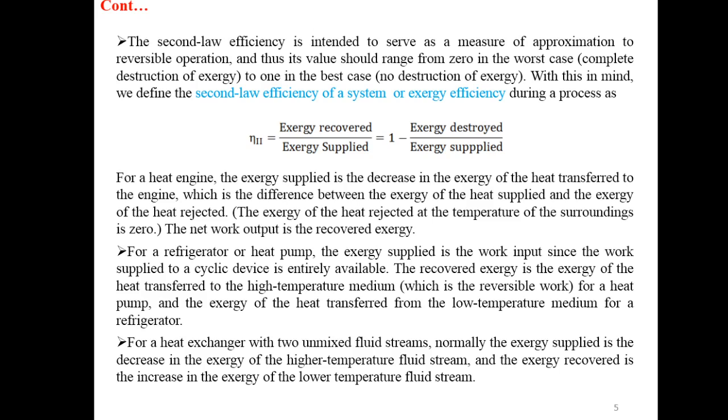For a heat exchanger with two unmixed fluid streams, normally the exergy supplied is the decrease in the exergy of the high temperature fluid stream, and the exergy recovered is the increase in the exergy of the lower temperature fluid stream.